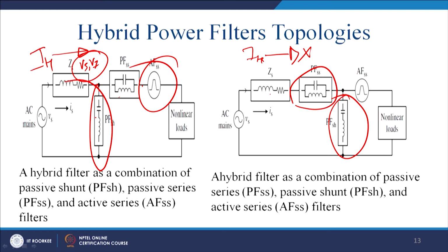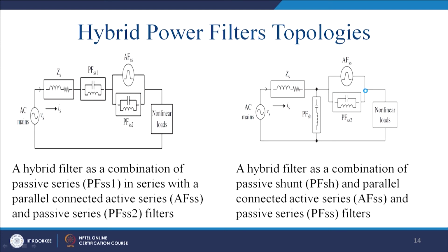Similarly, here it will block that fifth harmonic and the seventh harmonic voltages, and thus the current available here due to the fifth harmonic will be low, and that will again be shunted to the ground, and ultimately whatever you are left with, the voltage contamination of the fifth and seventh or other harmonics, will be mitigated by the series filter.